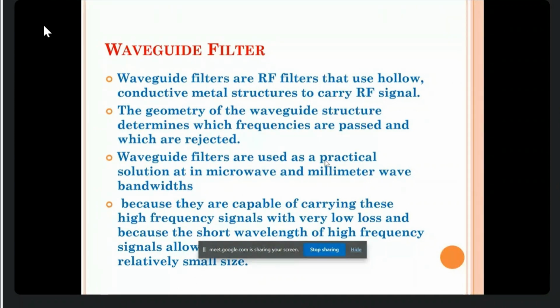Microwave filter means ceramic filter, cavity filter, planar or microstrip filter, or waveguide based filter. These are specialized filters used for microwave frequency, particularly when you process the signal in the microwave domain itself. That is required. I already mentioned that the other way is to convert to baseband or digital, where the design challenge in ADC is always there.